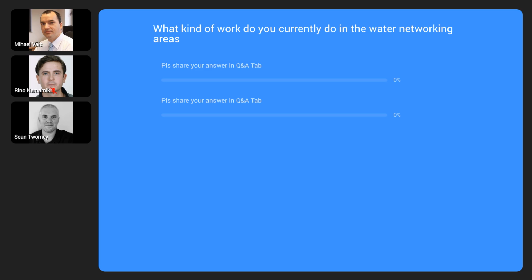So we got a question here, guys, on how the system would be applied to stormwater drains. Yes, so today we were showing the Softplan Wetplan module, which is for water distribution network design, hydraulic calculation and modeling. But we have basically a parallel module of the software, which is called Softplan, which is for the storm and sanitary networks. So you can use it for detailed design, hydraulic calculation and modeling of both gravity, pressure, and vacuum network, so both storm and sanitary is inside.